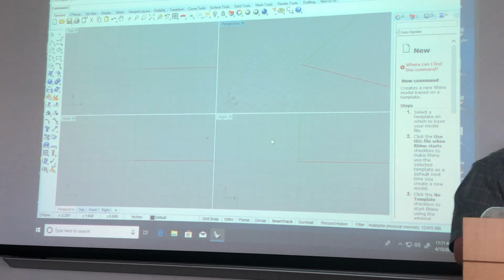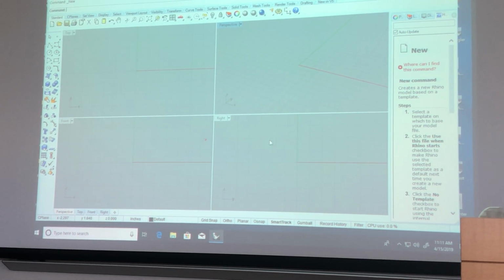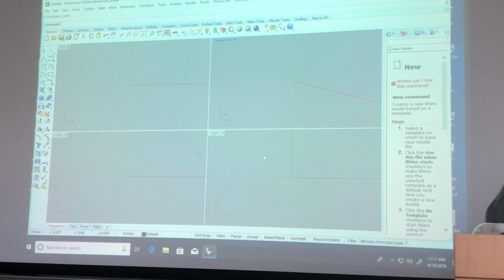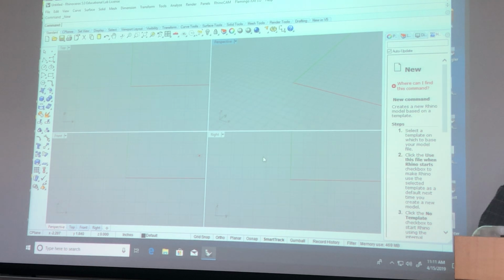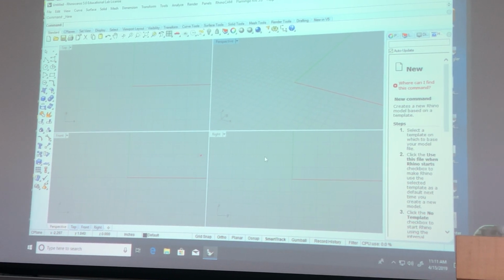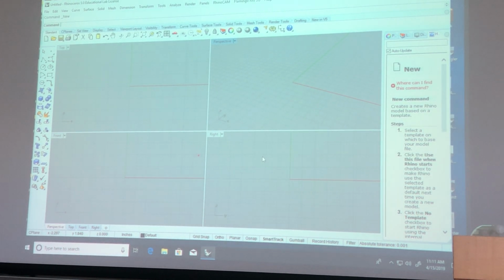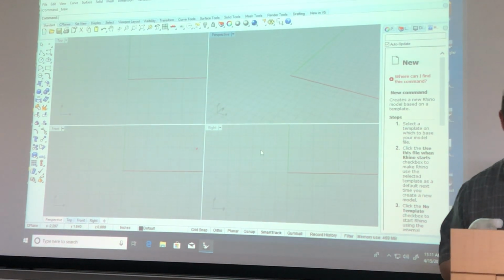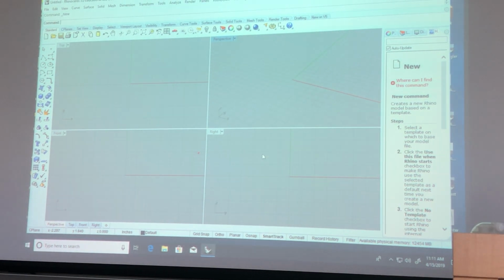You guys have been drawing in feet and inches, right? Alright. And now for 3D printing, you're going to draw things at their output scale. The 3D printers have minimum sizes and stuff. There's stuff you can't print. If it's too small, the printer won't print it. So let's start with no wall thickness can be less than 0.05 inches thick.